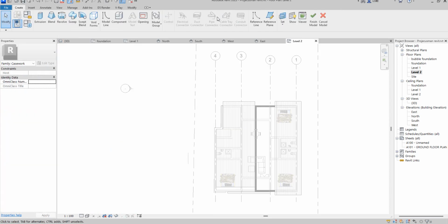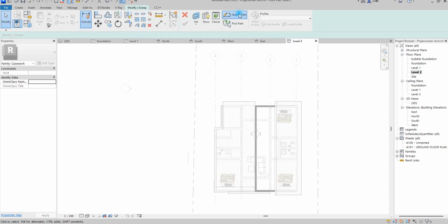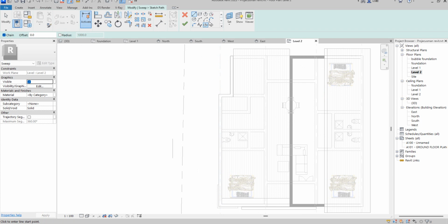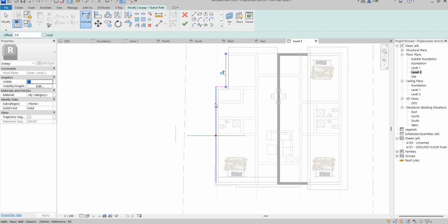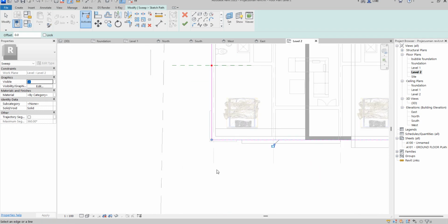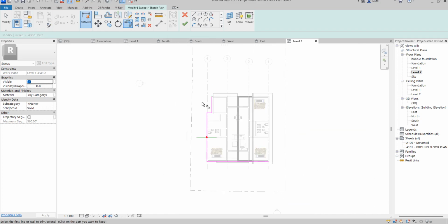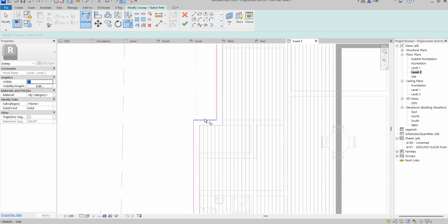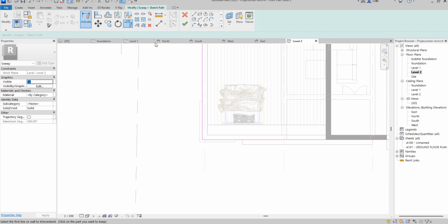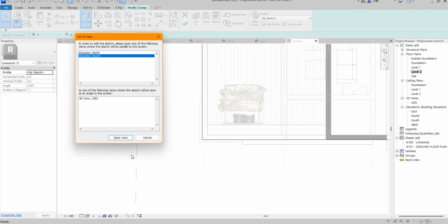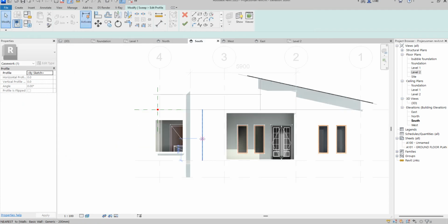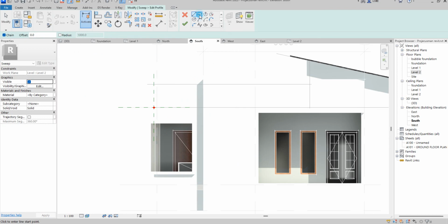So click here now. I will use sweep again. So instead of main, I'm going to pick line. I will just use normal line to do everything I want to do here. So pick all the external references line. So close it all. I think they are all adaptive now. Okay, so now you click finish, then you go to profile, start elevation, click open, then you drag and drop.